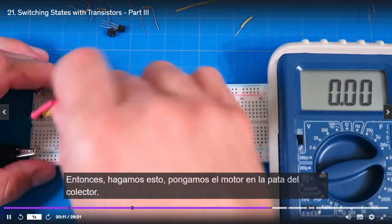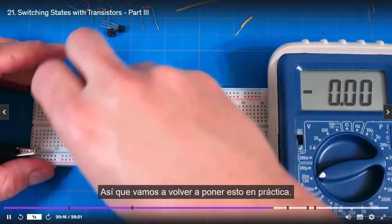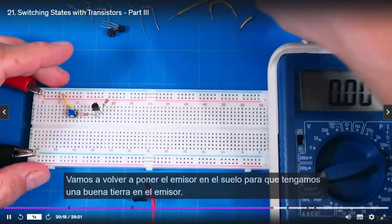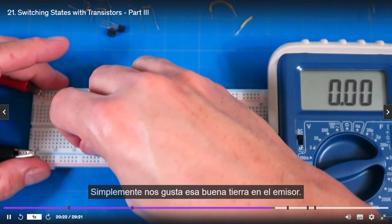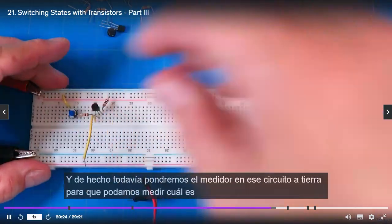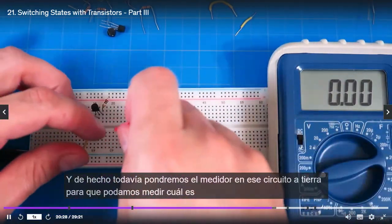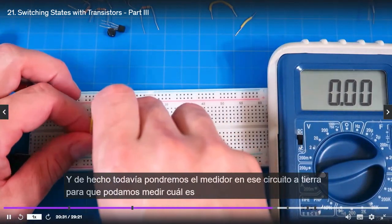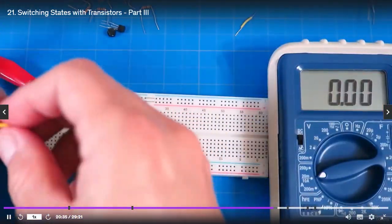So instead, let's do this. Let's put the motor up in the collector leg. We're going to put the emitter back down to ground, so we've got a nice ground on the emitter, right? We like that nice ground on the emitter. And in fact, we'll still put the meter in that circuit, going into ground, so we can measure what the final current is down through the emitter.